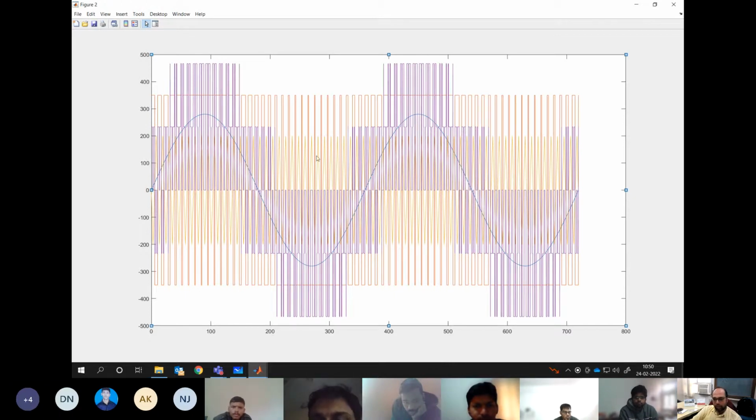So same analysis what you have done for 0.2 value of modulation index, which means you are dealing with somewhere here in this zone, which is close to the 0, somewhere around 0.2. Now if you increase this and go up to the near the peak 0.8, you will see a new voltage level coming over there, which will be 2 VDC by 3.